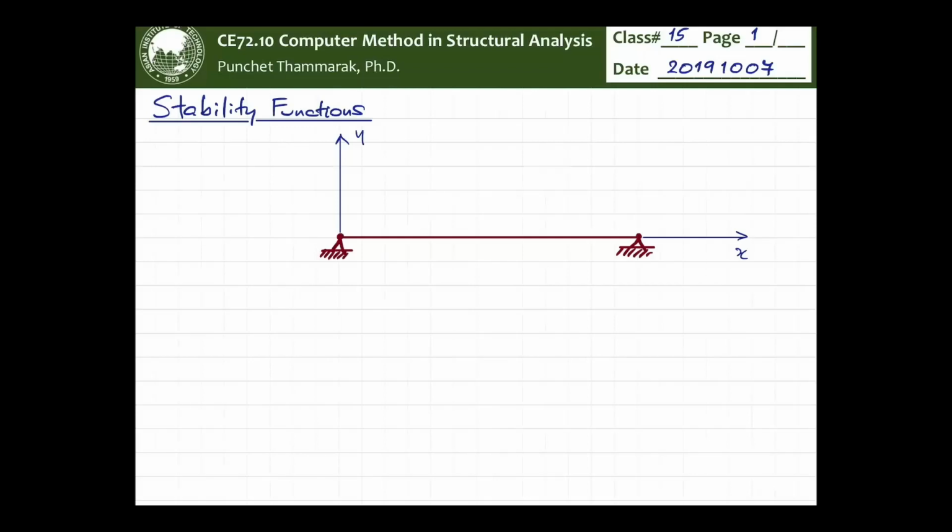You differentiate twice, you get curvature, and another derivative that you get for the shear, and so on. So we can draw the deformed configuration. Well, if we apply some moment, it is just our choice to apply, alright? As long as we cast the equilibrium equation correctly, you'll be able to get the stability function correctly. So I think that I'm gonna apply moment like this,